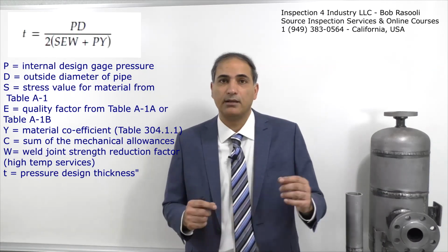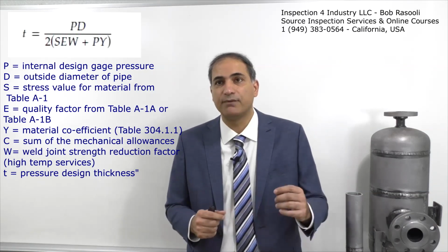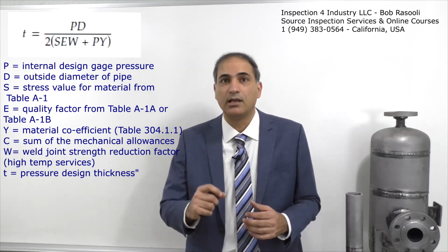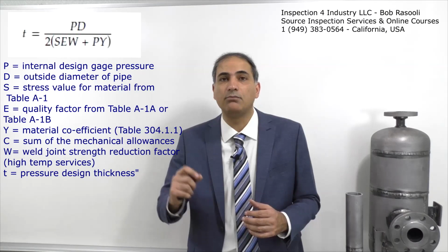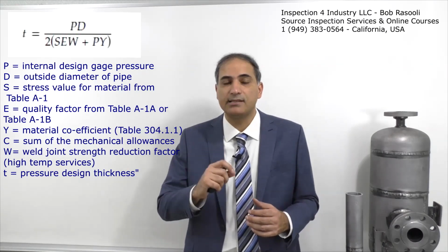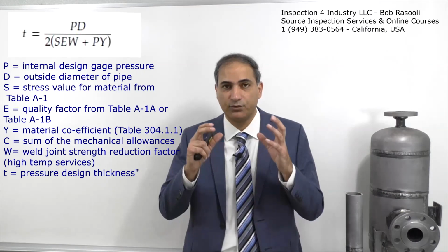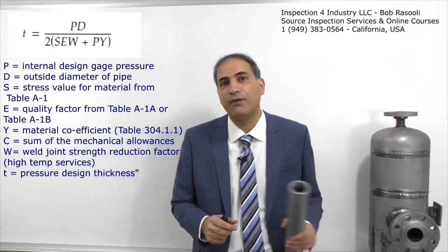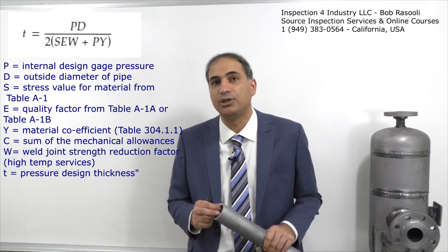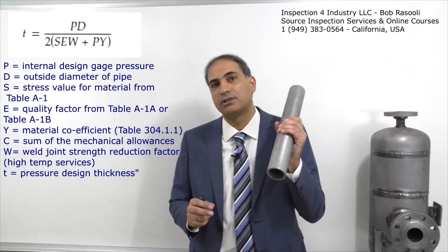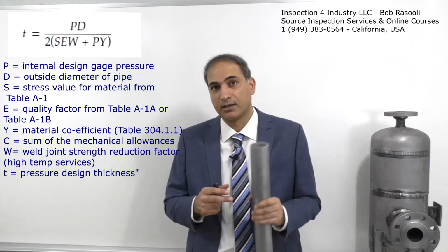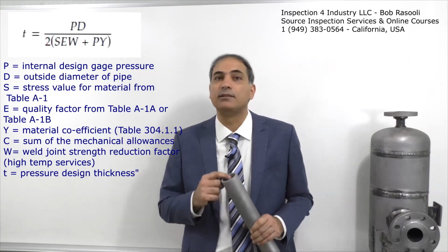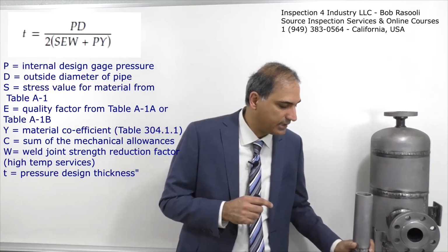the S has a reverse relationship with the thickness. So if you put the 35,000 psi, you are putting the stress at the yield strength, which is almost a deformation. You are putting the elastic to plastic transformation point, so you don't have any safety factor. I mean, if you put 35,000 psi, the yield point, in that formula, it means almost exploding this pipe under the pressure for which you're going to calculate a wall thickness by this formula. With this formula, you're actually calculating the wall thickness, so it's a very wrong thing.